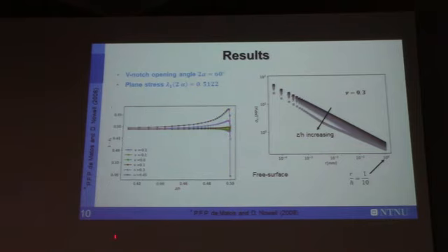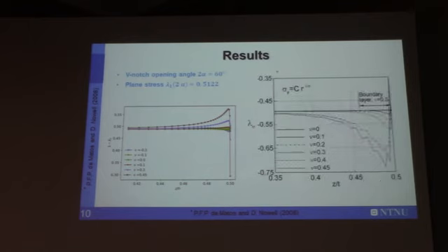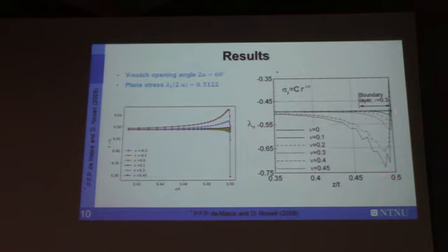So here is the result, also including a concentration near 0.5. This result is in agreement with a previous result of Matos and Nowell of the University of Oxford, where they saw that near the free surface there is a boundary layer, the region where the corner point singularity influences the stress field. Let's say that this work was for a crack.